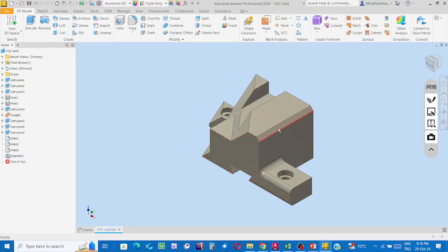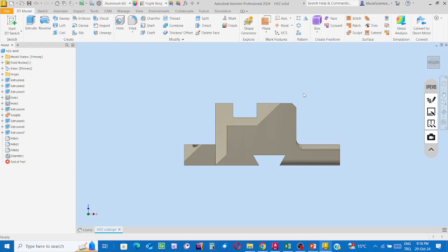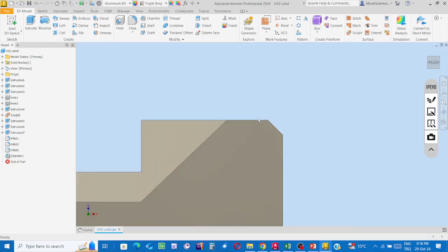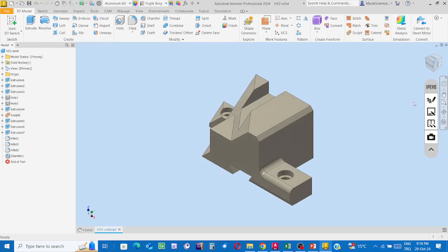You see, now along the edge I created not a cylindrical surface but a flat surface. It is called chamfer. And then see the chamfer sharpness angle. You see this angle is obtuse, that angle is obtuse, and the risk level is less, hand cutting risk is less.